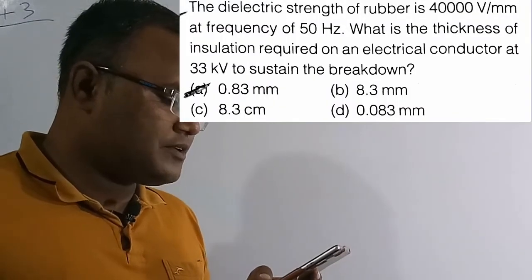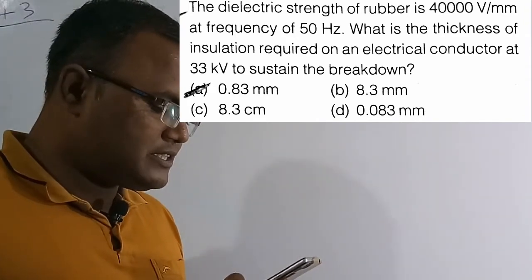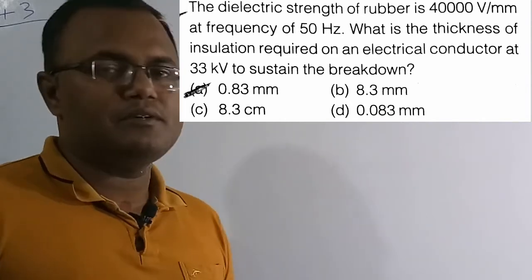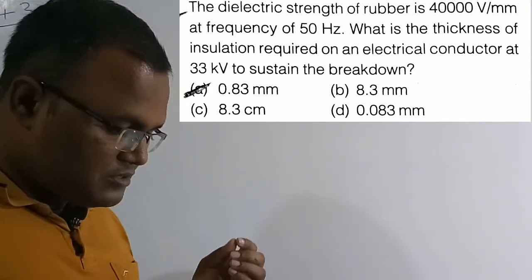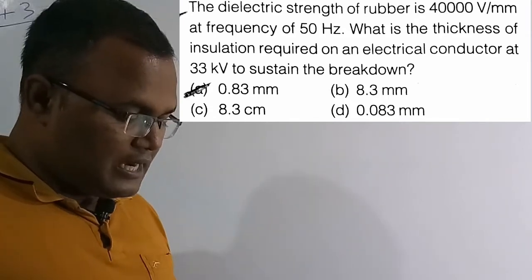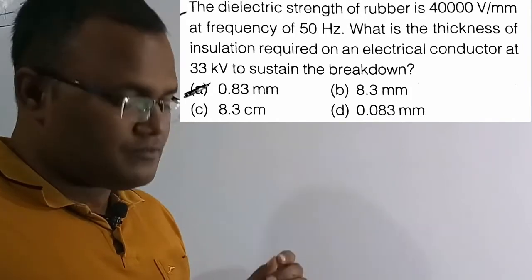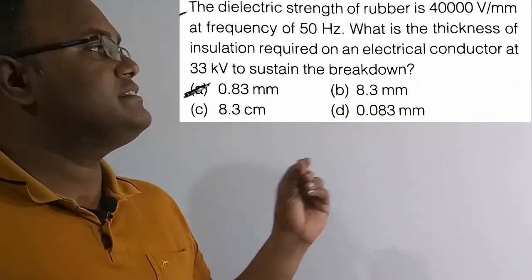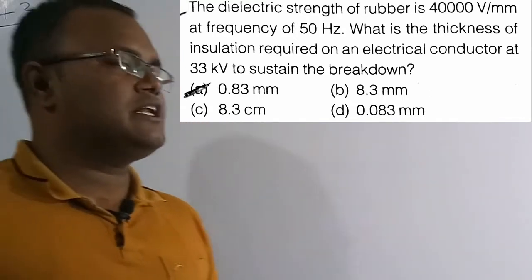Now we are going to solve the 43rd question. See the question here. The dielectric strength of rubber is 40,000 volt per millimeter at a frequency of 50 hertz. What is the thickness of the insulation required on an electrical conductor at 33 kV to sustain the breakdown? Basically they have given a conductor voltage of 33 kV, and the dielectric strength of the rubber above the conductor, which is 40,000 volt per millimeter at 50 hertz. What insulation are we going to require for this conductor with the given data? Out of these four options, option A, 0.83 millimeter, is the correct solution of this question.